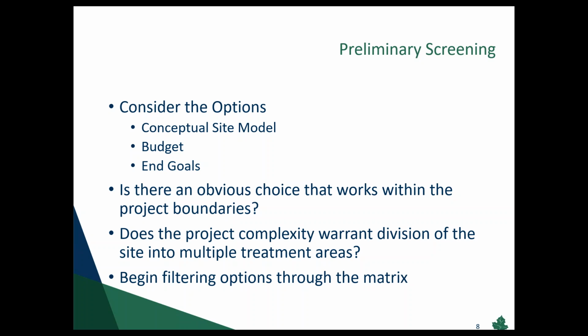We knew that wouldn't make our dissolved phase standards, so we followed that with a persulfate-based injection, which is a chemical oxidizer that breaks up the contamination into CO2 and some innocuous gases. But we also knew that we couldn't over apply the persulfate in that area based on some nearby utilities.